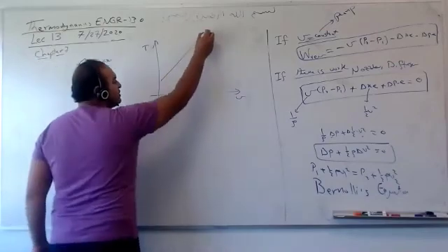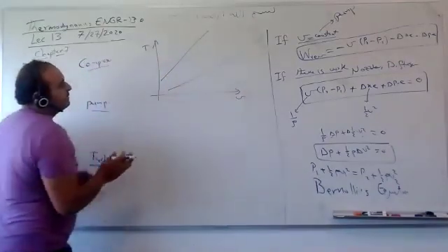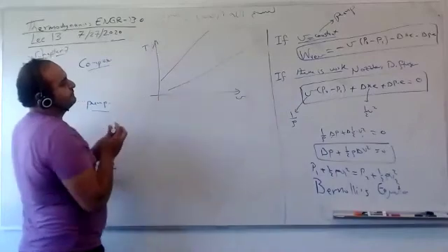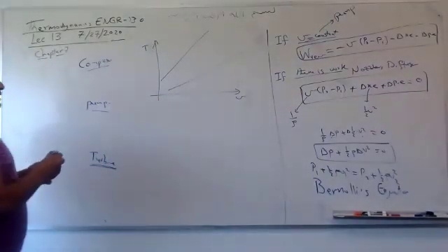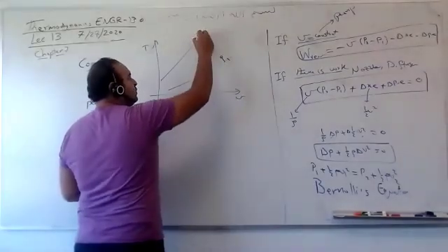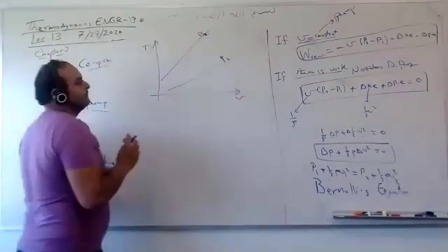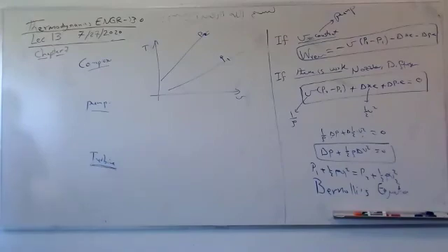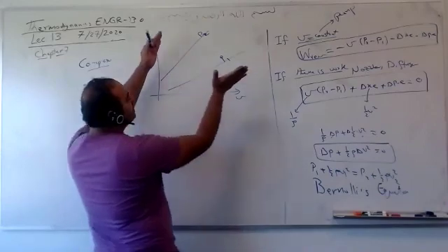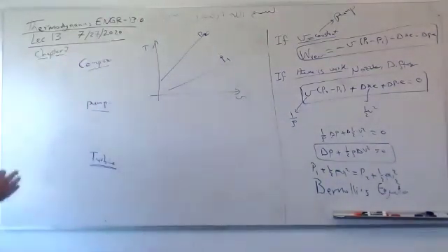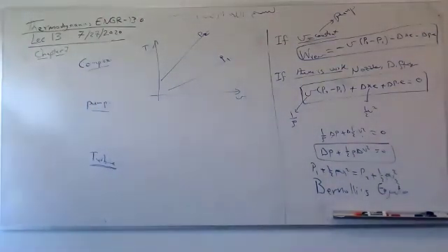The gas has constant pressure lines like this. The pressure lines are diverging. This is the key of all designs. The pressure lines P1 and P2 are diverging. When we go to the Rankine cycle, Otto cycle, Diesel cycle, Brayton cycle, these cycles always have pressure lines diverging, going away from each other. This is the key part of all devices.